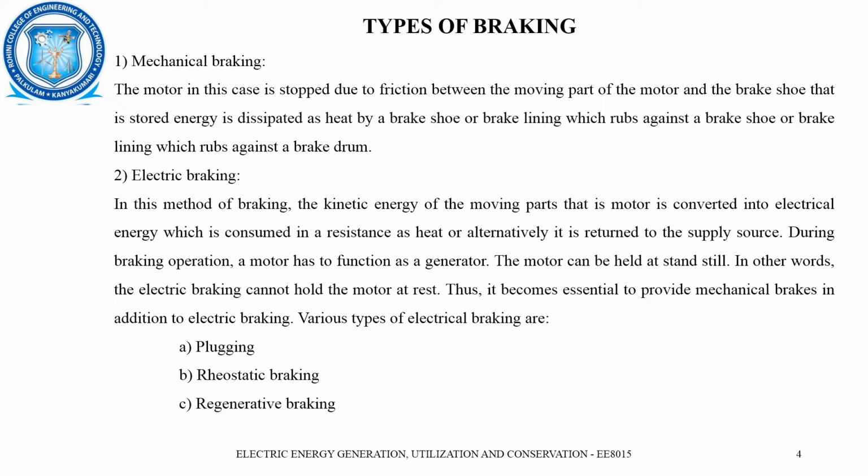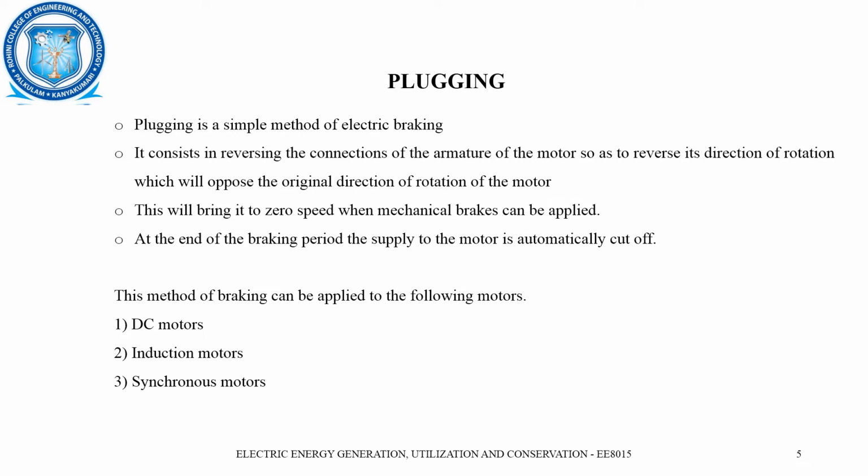During the braking operation, the motor is made to function as a generator. The motor cannot be held at standstill, otherwise, the electric braking cannot hold the motor at rest. Thus, it becomes essential to provide mechanical brakes in addition to the electrical braking. Then we can see how it works, starting with the plugging process.